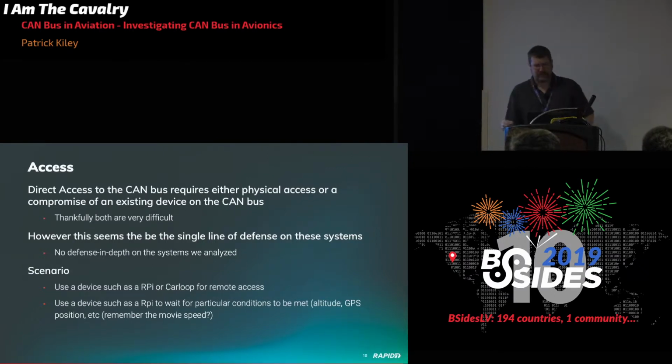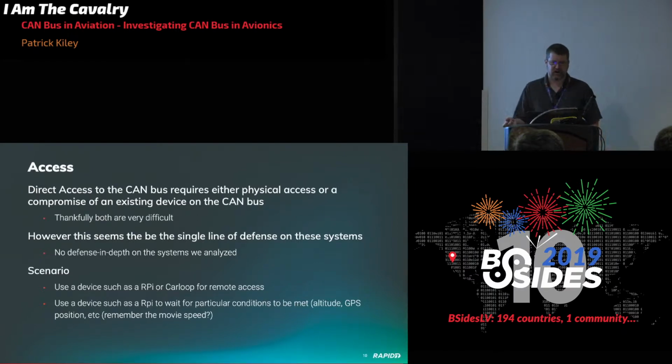So, getting right into it, let me show you some example messages. What I have right here is the arbitration ID. This is what's called an extended CAN ID because it's 10342200. That's in hex. And then we have bytes 1, 2, and 3, DE4714. What I found is that from this arbitration ID, DE4714 meant oil pressure. Now this was on a system that I built, and I just built up the telemetry for oil pressure, and I set up a little variable resistor on my kit so I could simulate the various oil pressure conditions.